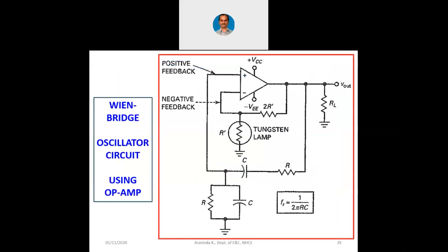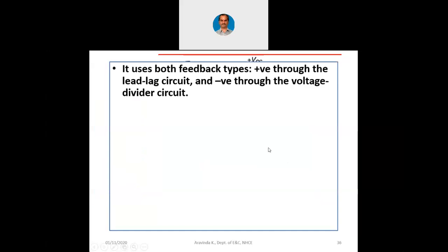Please recall the circuit. I am going to show you again. See, you have this positive feedback. Can we say it exactly as a negative feedback? Negative feedback is also there. Positive feedback is also there. Now, should we consider it as an inverting amplifier or a non-inverting amplifier? Now, when the feedback is coming here, it is basically working like a non-inverting amplifier. So, when it is working like a non-inverting amplifier, the gain is 1 plus RF by RI. That is the point here.